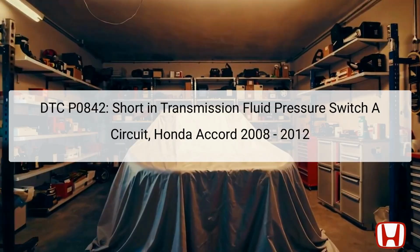The Diagnostic Trouble Code, DTC P0842, indicates a serious issue within the transmission fluid pressure switch A, specifically for the second clutch in a Honda Accord from 2008 to 2012. This code is generated when there's a short circuit in the transmission fluid pressure switch A circuit, or if the switch is stuck in the on position.